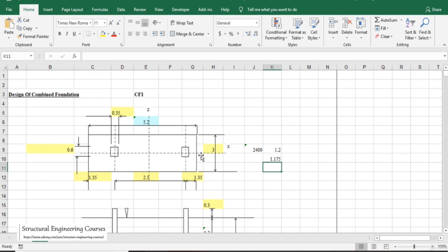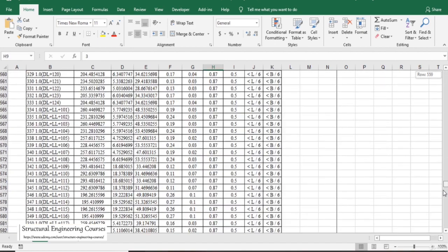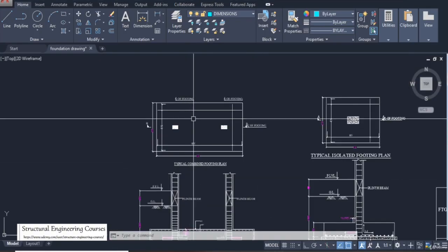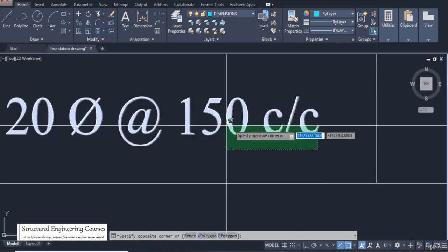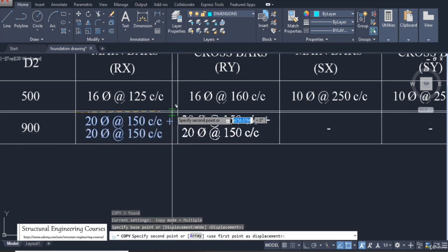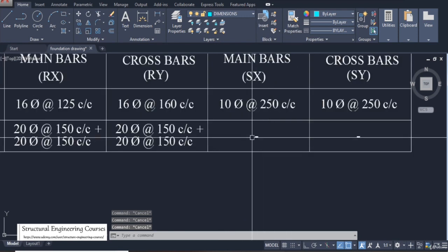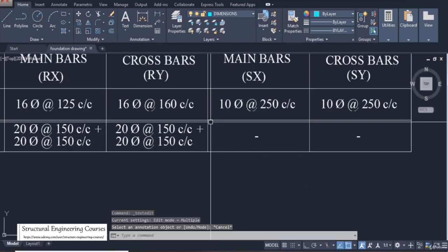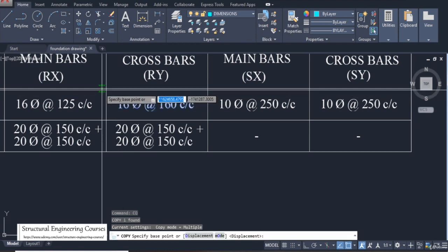But as the bending moment was not the governing requirement, we are not considering both the different projections here. But in some cases it might happen that this side projection may become very high and this side projection very low, so the higher projection shall always govern the bottom reinforcement design. So coming back to our point here, we can just copy paste what we have written here, and similarly for the top reinforcement we can provide 16 dia at a distance of 150 mm center to center.